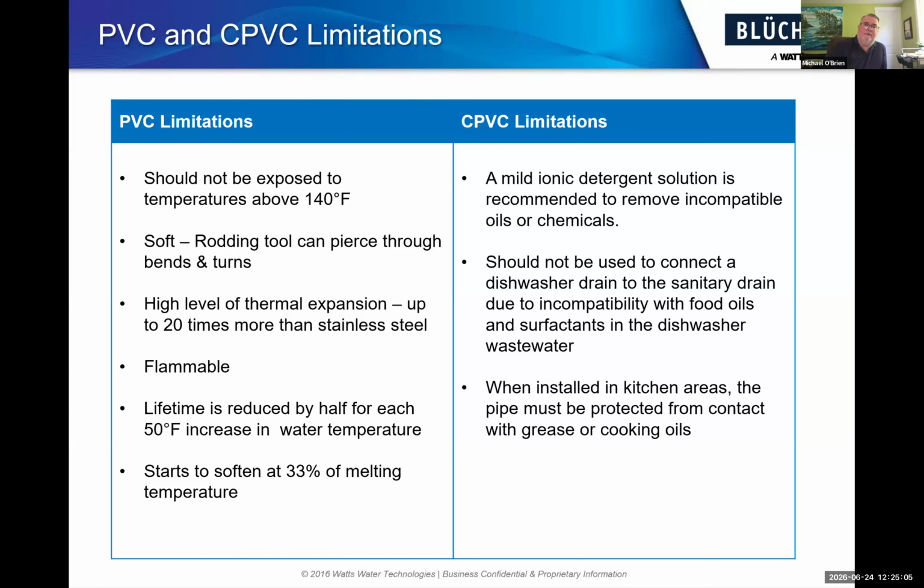So that leads to various issues. If it's a plastic channeled trench drain, and you're dumping some hot water through it, that PVC is going to want to move. If it's installed in concrete, it won't be able to move out, so it will start to kind of collapse in on itself a little bit.